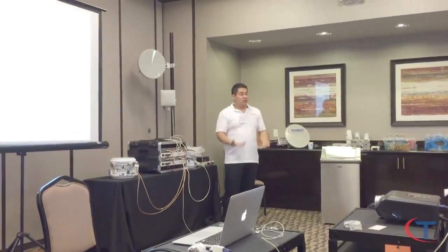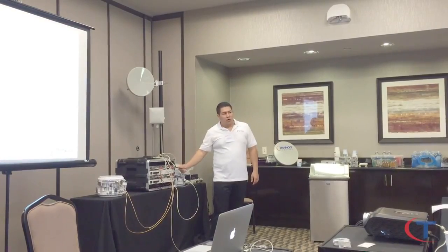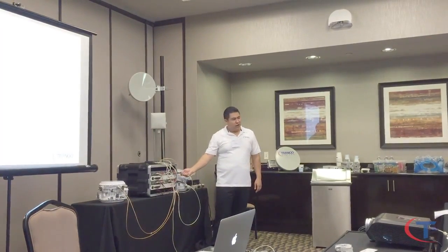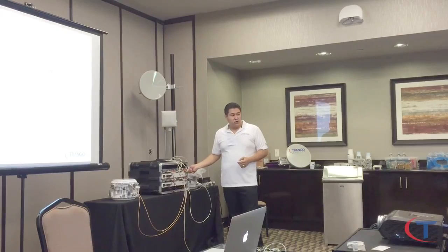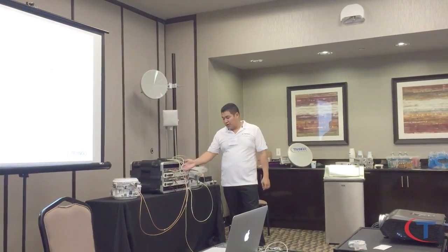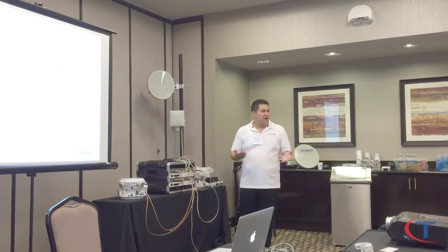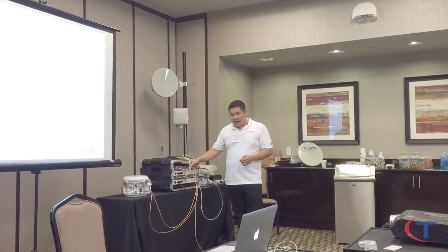So typically what installers do is they color code, right? They can put white and green, white and blue, white and red here, and then on the top of the tower, on the actual ODU, you will have another color coding as well, so you know which IF cable goes to which IF cable. On labeling as well, your Ethernet cables, you can just do a quick label for those with a little printer, not a big deal. And label the IDUs themselves.